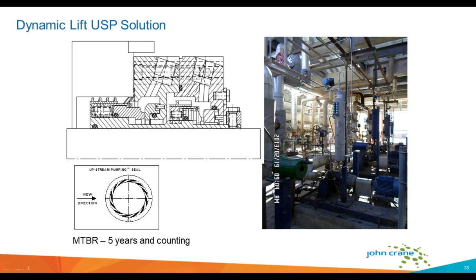It just consisted of a dedicated line of water or clean condensate piped directly to the reservoir that you see in the picture, and then a regulated pressure of 5 psi on that dedicated water line. So over time, as there was some consumption of the water by the upstream pumping grooves, and the typical consumption rates are very low, between half to a gallon per day usually, or a few gallons per day depending. But as the seal consumed the water, the regulator will open up to adjust and equalize that pressure.